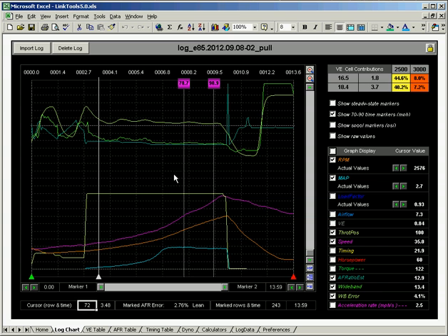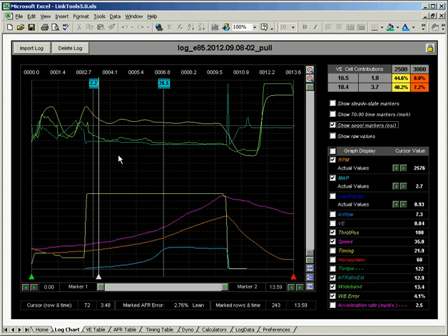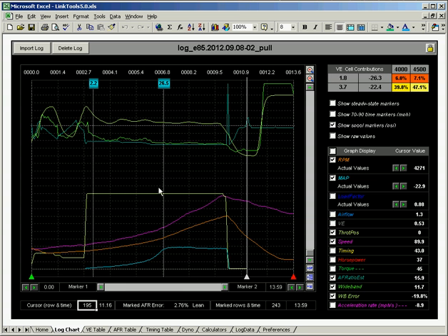If I click show spool markers, these are the markers I was telling you about earlier where it calculates your spool. You can see right here that based on my RPM setting and being above 80%, it set the starting spool point at actually 2.2 psi of boost. So I would probably want to lower my starting RPM point, and it would find something more back here.